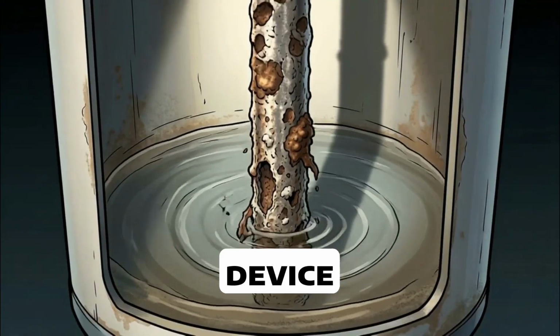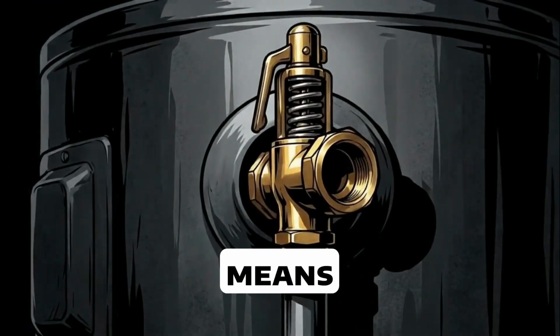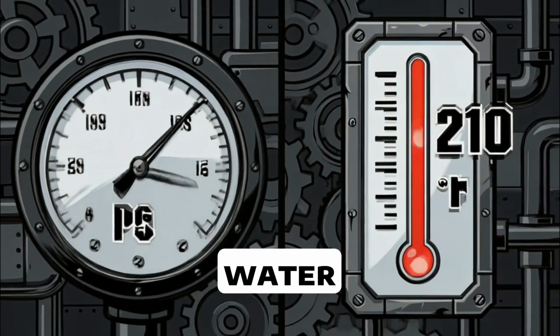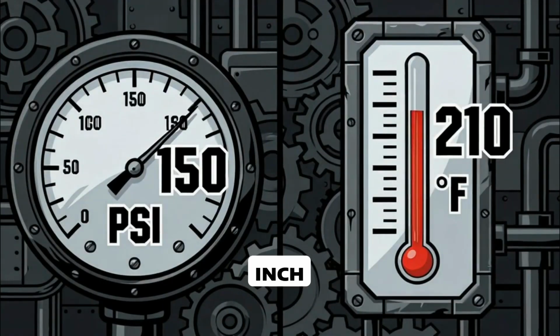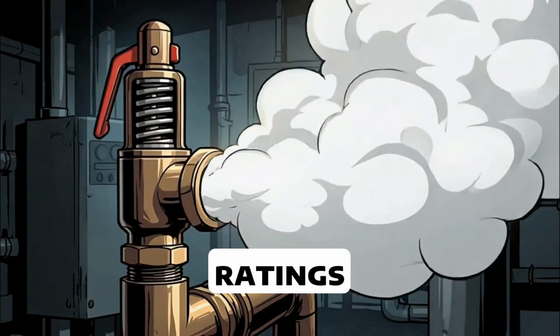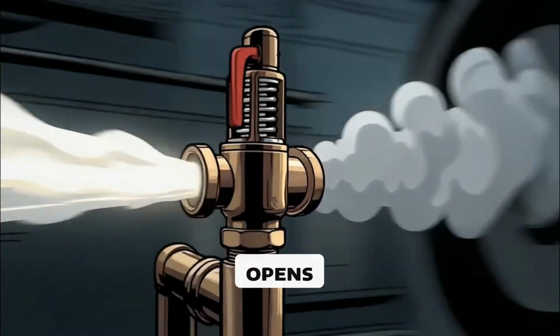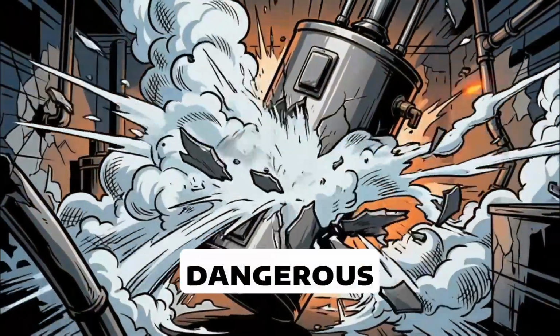Now, the safety device you must know. The T and P relief valve means temperature and pressure relief valve. Many residential water heaters use a pressure rating around 150 pounds per square inch and a temperature setting of 210 degrees Fahrenheit, though always follow manufacturer ratings. If pressure or temperature rises too high, the valve opens to protect the tank. Without it, the tank can become dangerous.